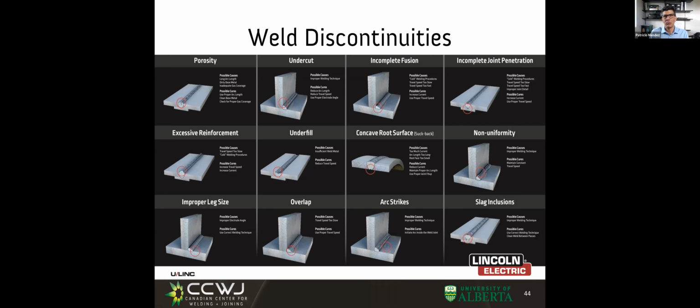But if you give the current, from all the mechanisms of welding, if I know the current, I know how much metal I'm putting down. And if we say what this cross-section of the weld should be, or the reinforcement, or the size of the groove, essentially I'm giving a cross-section of material that we need to fill.